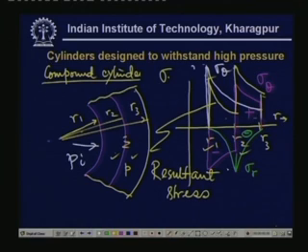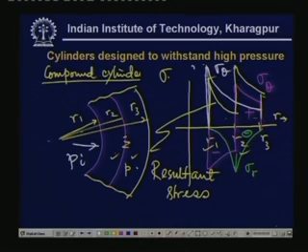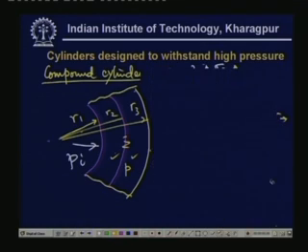I have said already that the outer cylinder has an inner diameter which is smaller than the outer diameter of the inner cylinder, and this difference between the 2 cylinders, the clearance, is very important, and it is the guiding factor in deciding the effect of P. But how to get that value of P is a statically indeterminate problem and cannot be solved unless you bring the strain into account. If you do that, then what you have is